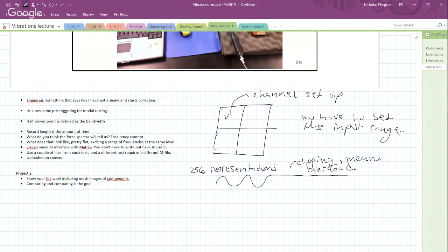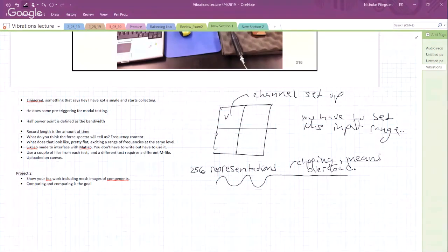Digital noise, you're down there. So you're going to have a lot of noise, and what we say when we're taking measurements is that you're going to have poor signal to noise. So that's why on an analyzer that you use for lab balancing purposes, 3 green indicator lights, those should be on. No red lights.